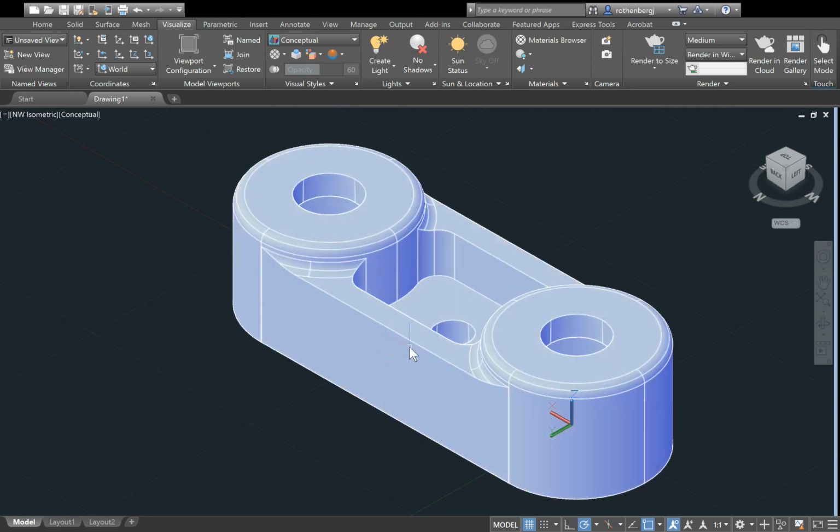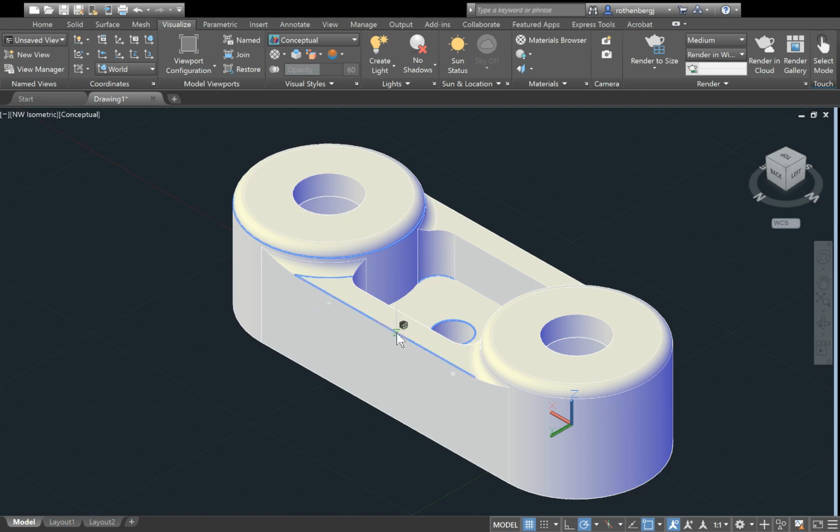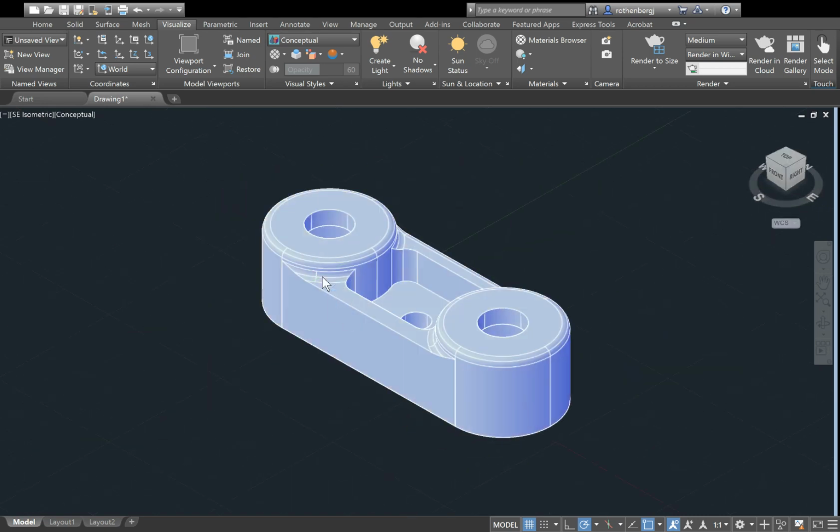Okay, now we are going to be doing the outer edges. So once again, fillet, hit enter, select the object. However, now we are actually going to need to use the chain command. So after it asks you for the radius and you hit enter, type in the letter C for chain, and then select the edge again, and it should select all of the lines in that row. Hit enter, and it should do that whole section, so you don't have to select them all individually.